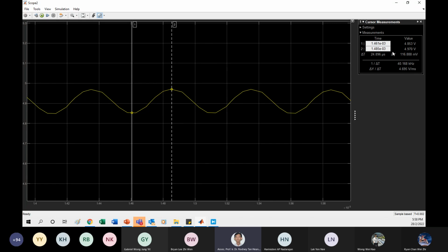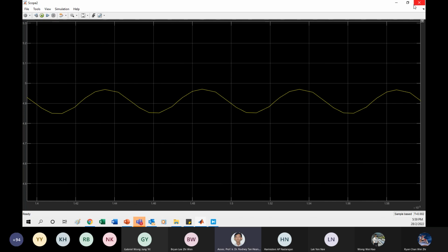So you'll be around 0.11. Okay, it's less than 2%, less than 2% of the ripple. If you look at the voltage here, you see it's around near 5 volt on the so-called positive side, and the negative side will be right near 4.8. So these are the ripple. And this ripple cannot be avoided. It will be here.